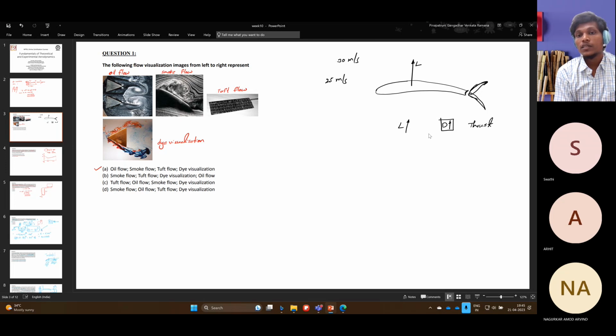The priority in the landing is to decrease the speed and to decrease the lift. Decreasing the speed means to slow down the aircraft, but that is not all we are doing, right? Because we don't want the lift at the time. We need to spoil the lift, which is why we call it a spoiler.